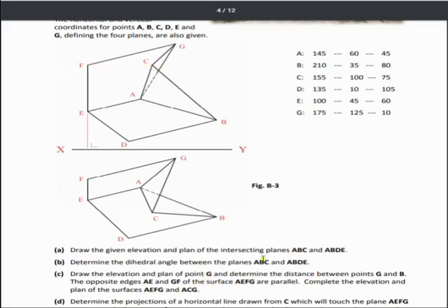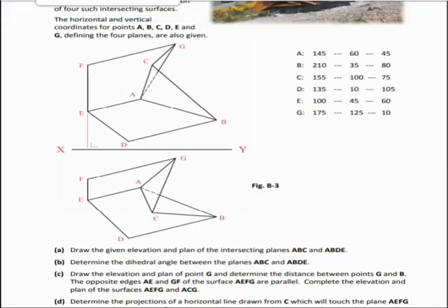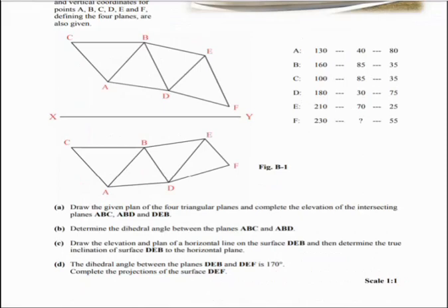Now what we're told in the question is we can bring that line that's on this surface down to plan here. So we can draw that line down onto plan. Then in plan we know it's 55 from C. So that allows us to construct an arc from C scribing onto this line here, which we'll have to find, and then we'll be able to complete. So if we look at the solution to this, we'll see how that is actually done.